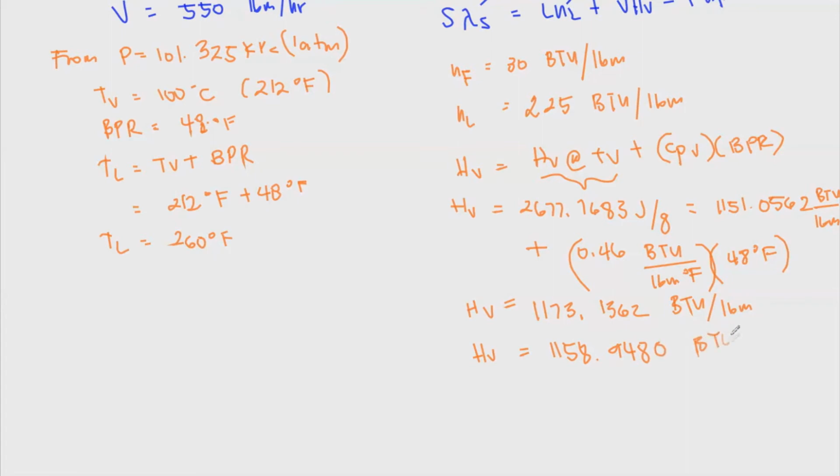So this is the value obtained from using this HV and then accounting the sensible heat obtained from the boiling point rise. And this one is obtained from using just the direct TL, but using 0.1 megapascal. So probably the difference is kind of low because the pressure that I use is actually 0.1 megapascal and not 0.101325. So it can still increase when you use double interpolation. So I'll leave this with this value, and of course I will be deleting this because this is the less accurate one that I did. But anyway, you can do that as well in your solution.